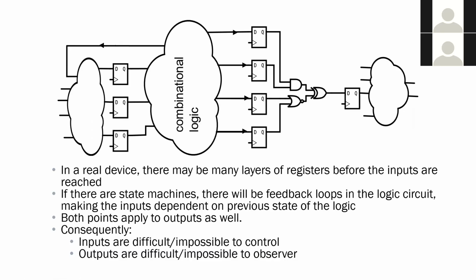And it's also important for you to appreciate that in the structure of the logic in an ASIC, you have registers, or groups of flip-flops, that are sending data into combinational logic, and the outputs of the combinational logic are captured by the flip-flops. And you have multiple such stages in a typical sequential ASIC, where flip-flops send data into combinational logic, the output is captured by flip-flops, and those flip-flops send data through some additional combinational logic, and so on across multiple stages until finally the data arrives at the output.